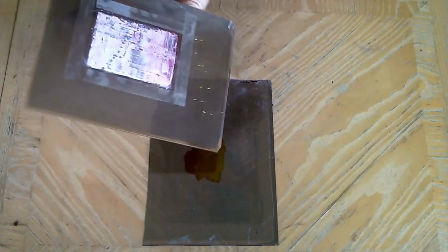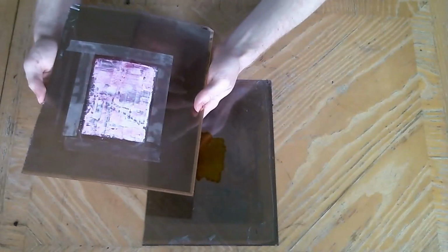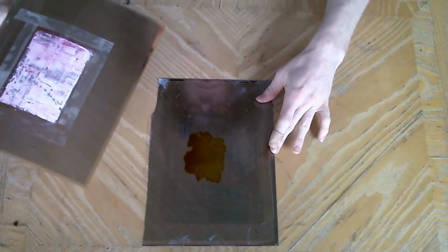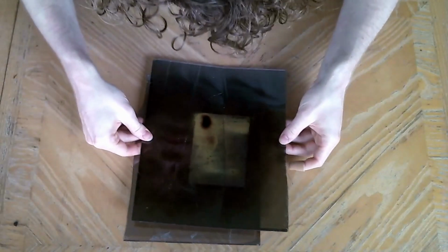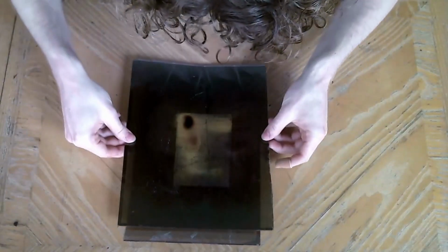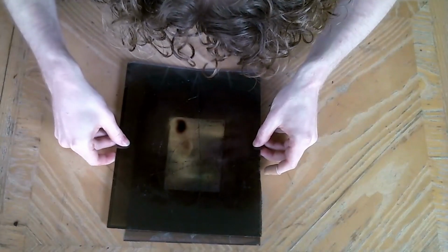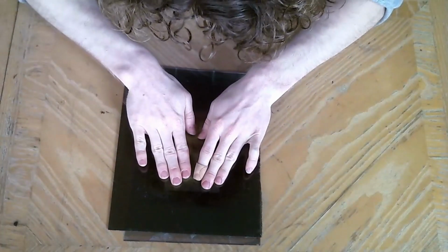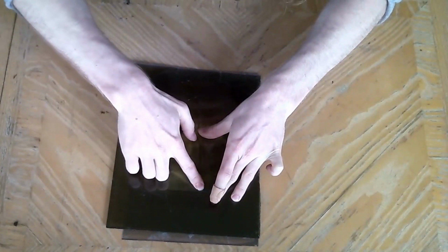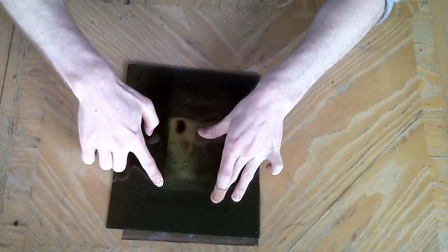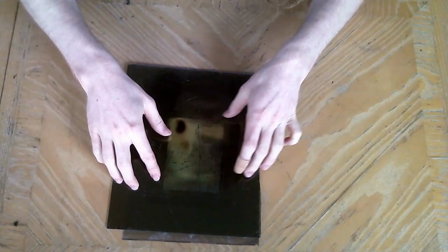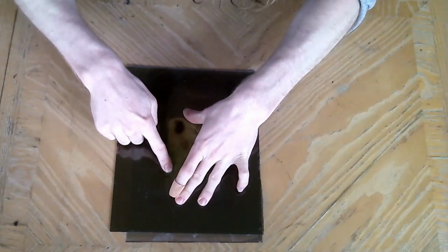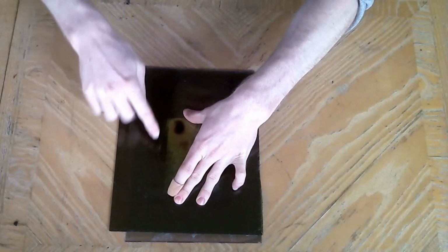After we do that, we are going to attach a clamp to both the top and the bottom layers of glass. I prefer to attach this clamp on the broken sides of the glass. I found that that is much more conductive when using monitor glass. As you can see, I leave a little top tab open and a bottom tab open so that we can attach our gator clamps there to create our circuit. So I'm just pushing the two together and ensuring that that tape is sealed here in this clip.